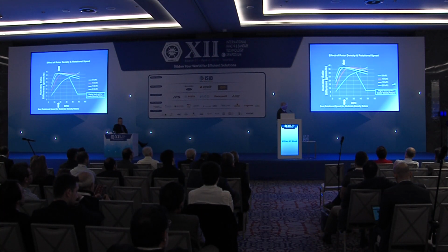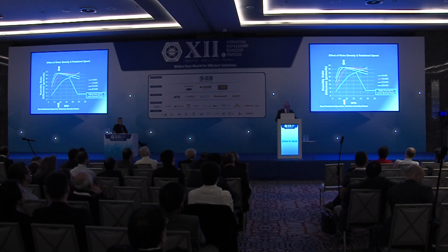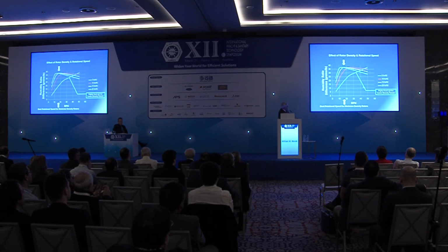So if I have a rotor that's 20 pounds per cubic foot, I'll usually operate around 12 revolutions per hour. That's how fast these rotors typically go. And that's what you'll see mostly. Most of the rotors are rotating at 10 to 20, or 12, 15 revolutions per hour. The rotor that I showed you that was no longer made was at 5 pounds per cubic foot, so to get the optimum, you have to rotate that faster.